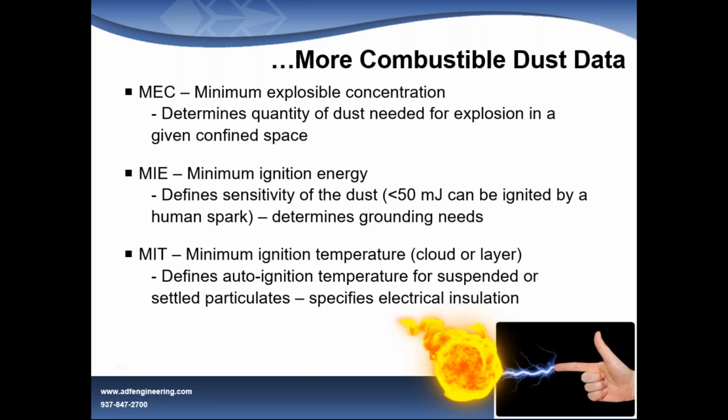There is another end to this. You can operate above the explosible concentration where you don't have enough oxygen. Then it gets into limiting oxygen concentration, which is another thing.